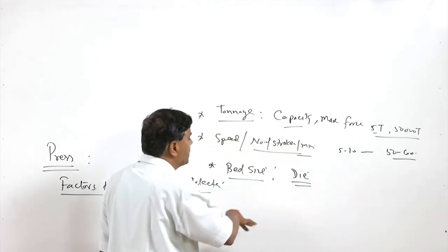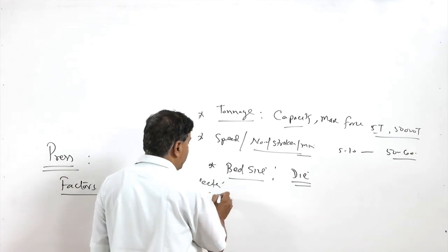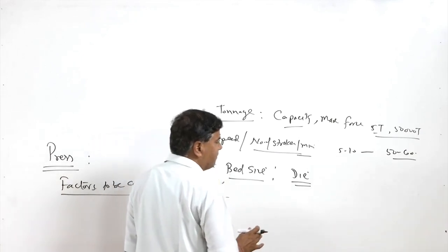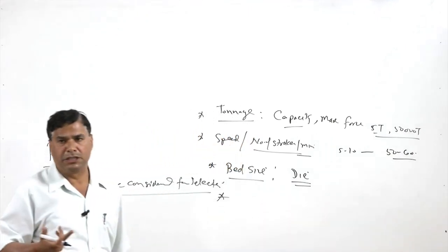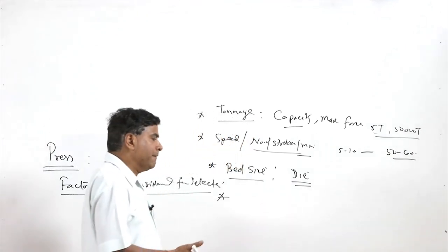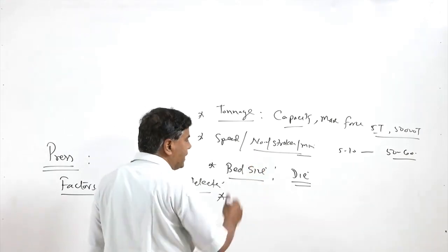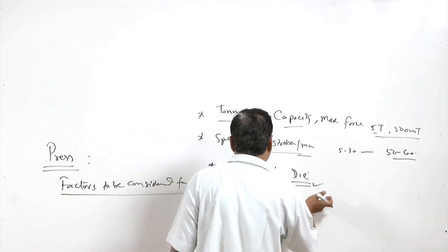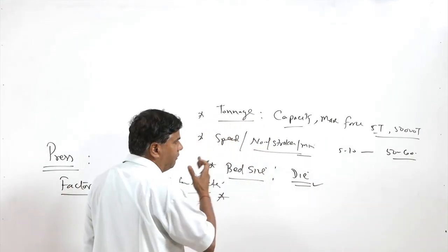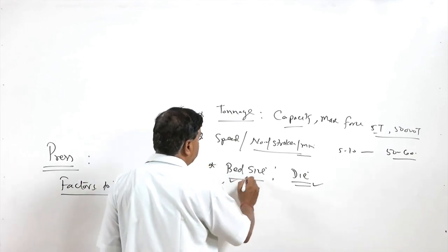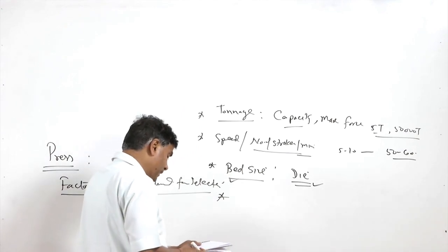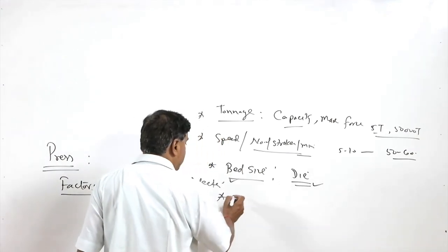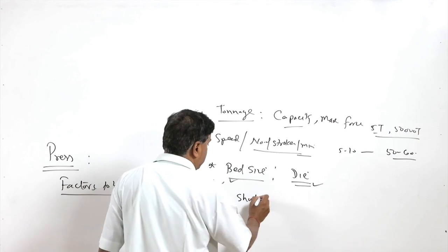That bed area or bed size is to be used for making the sheet metal product of the desired size. Accordingly the die is made and must be accommodated into the bed of the press, so a bed of suitable size or area needs to be selected.